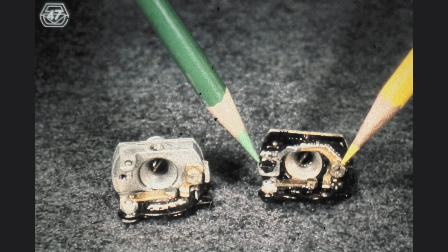When adjusting it, you loosen the screw indicated by the green pencil and only slightly loosen the screw indicated by the yellow pencil. This condition enables us to rotate the shoe around the yellow screw. It then becomes possible to change the position of the rotate detent shoe by very small increments and not lose that position when you retighten the screw indicated by the yellow pencil.